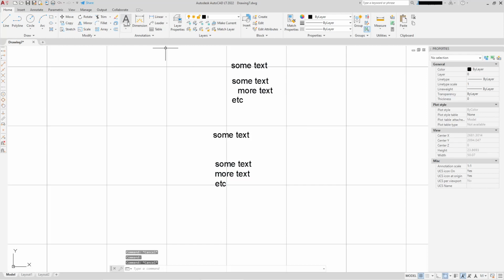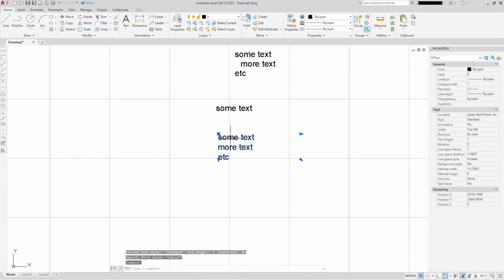Whatever you drew last will be set by default in the top box there. So once you select single line, it's got a blue line under it, which sort of means 1 line, I guess. So once you've set it to multi-line, you don't have to keep using this menu. You can just hit the A up there. And it has some nice properties.